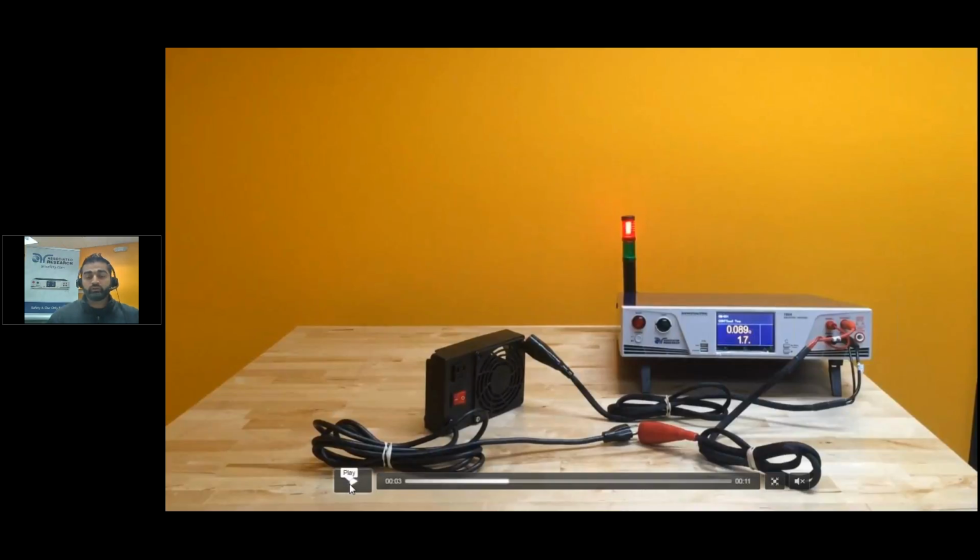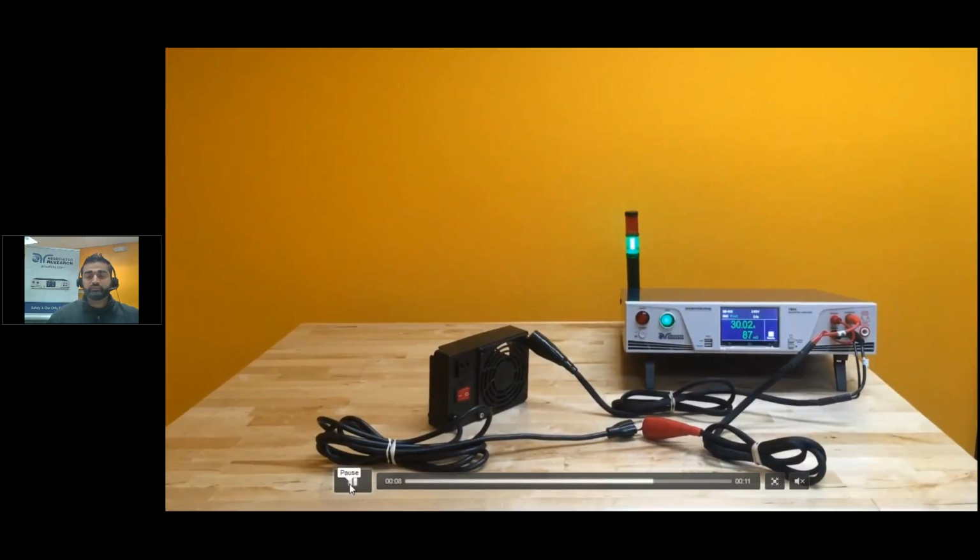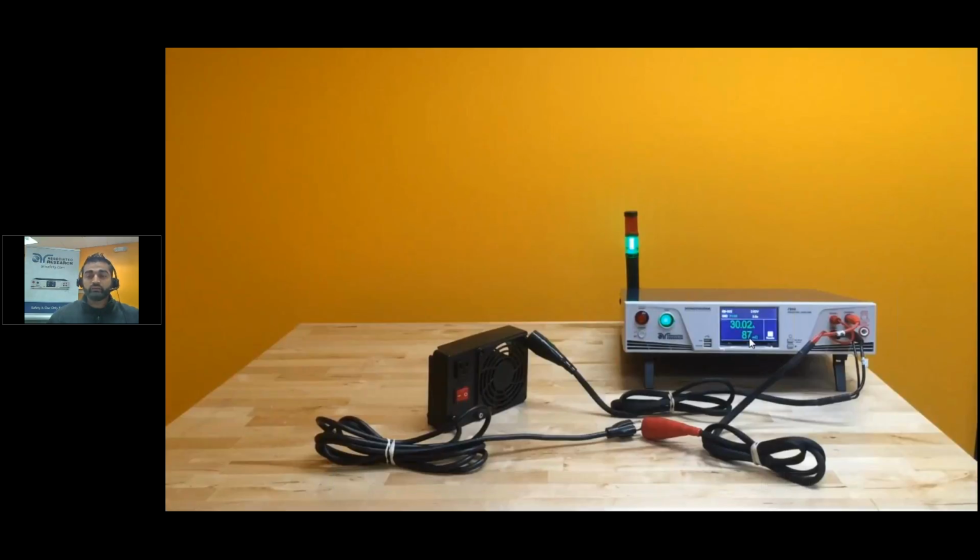But again, this is a low current test. If we were to do the same test, now we're running a ground bond test. At this point, we ran 30 amps of current, and the resistance was still around 87 milliohms for this ground circuit. So again, we ran the ground continuity test. It gave us a pass, and we ran a ground bond test of 30 amps. The circuit was good enough to have 30 amps go through it and still not break open.